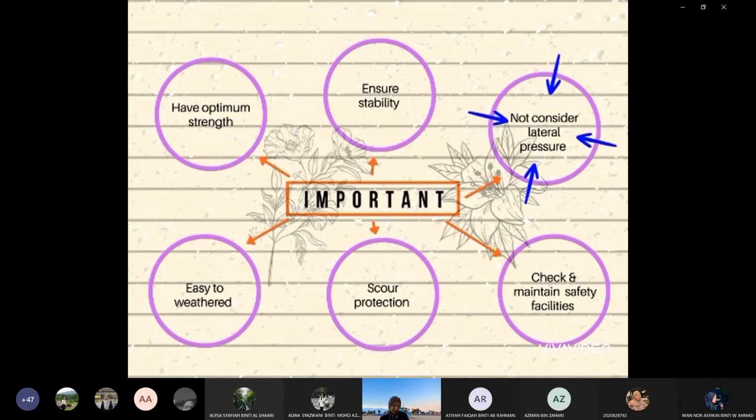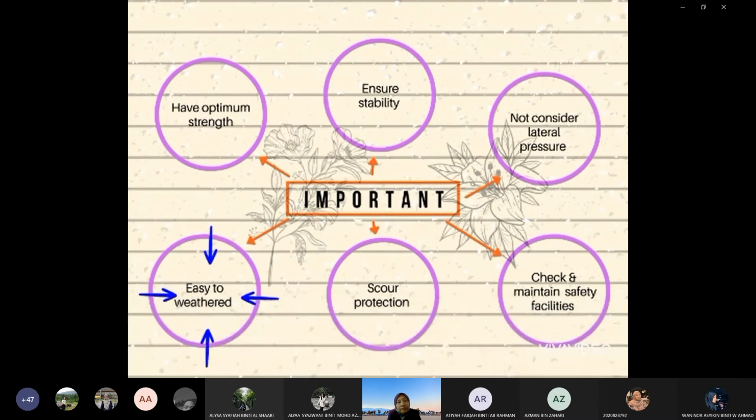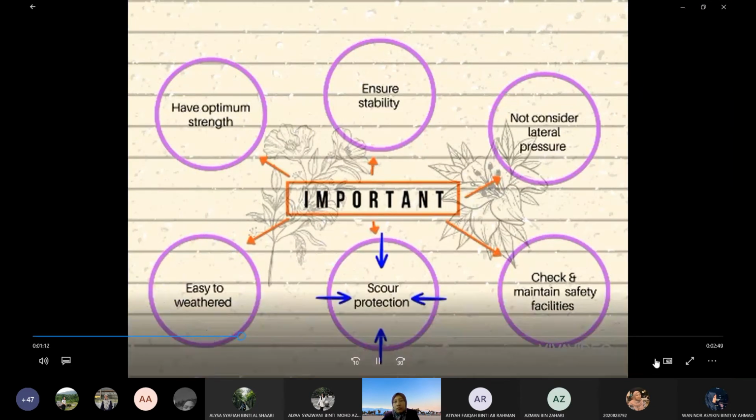Furthermore, slope protection should consider lateral pressure of slope stratum, so that it should have enough stability. Next, rock slope or lower slope with silt, fine sand are easy to be weathered, especially under poor climate and hydrological condition, so it should be protected in time after earth and rock construction.